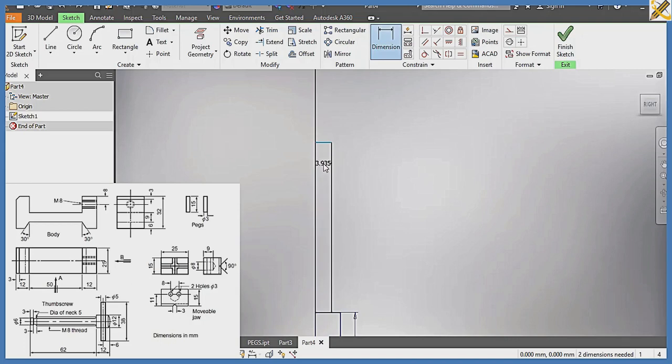Dimension this area to be 4, because the area is M8. Okay, after doing that, towards the top here we have the neck, which is diameter 5. So pick your circle. After picking your circle, you can produce a circle of diameter 5. Enter. Then tangential constraint from here down here. Okay, so then we check the measurement from this edge to, okay, I think they are on the same plane there, so settled like that.